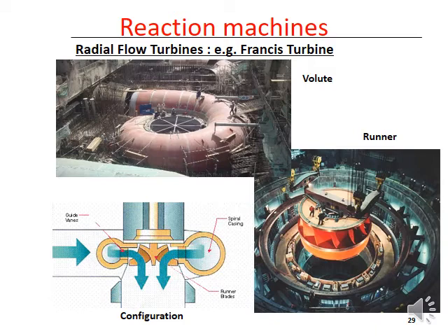There are about 8 or 10 power stations and the discharge is about 60 cubic meters per second, but the elevation head available is not that high, maybe 5-6 meters at one place. So axial flow type turbines become more efficient, and all the installations there are axial flow type turbines. We will see them soon in the next slide.